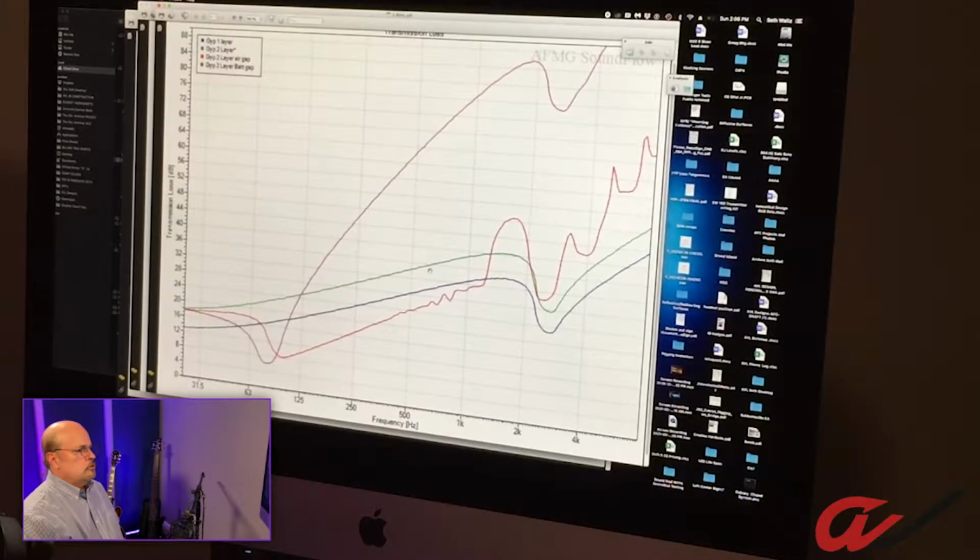Then this is gypsum, 2 layers, directly applied over the one, and you get an increase that you would expect based on having 2 layers, but you also have some variances that occur up here in this frequency dip. Now, the interesting thing then is let's put an air gap, and in this case we put a 3-inch air gap between 2 layers of gypsum. Look what happened. Having that air gap created a resonance and spring condition in between the materials. It created a whole bunch of weird anomalies and lowered the overall performance of the system dramatically.